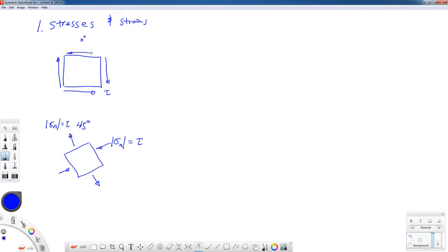You see these two arrows, they're pulling away from this particular corner. It's like it's putting the net resultant in compression on that plane. So that's why this is in compression here. And at the same time, these two corners in the upper left are both kind of pushing together and putting this side in tension.